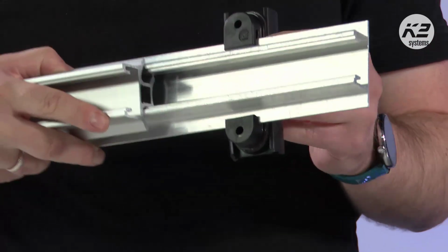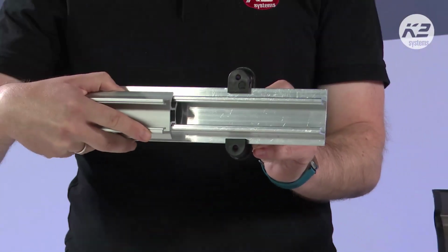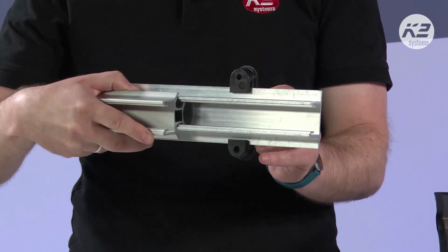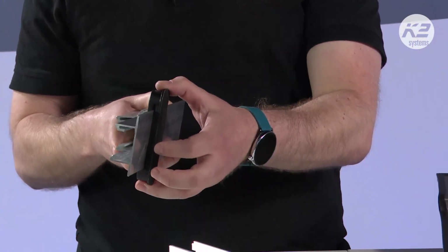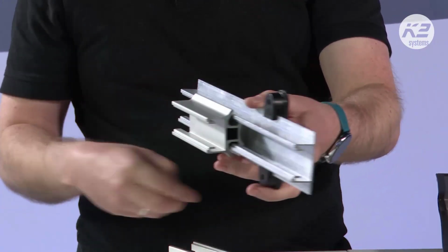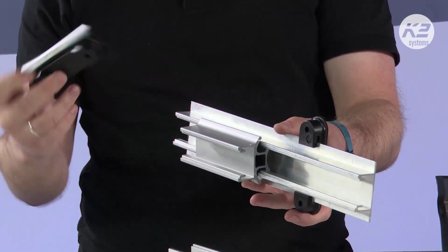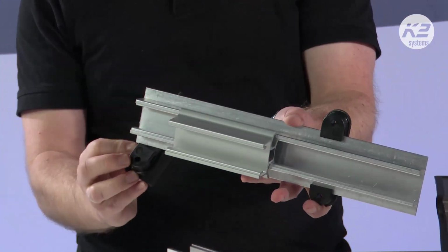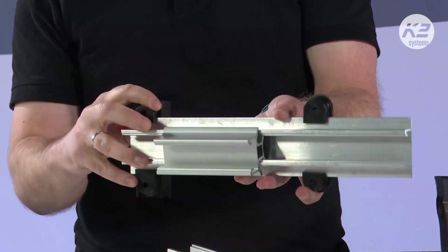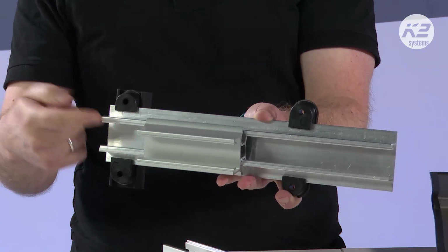You install two basic clips on both sides of your roof. You just bring the BasicRail inside, but now it can go up. And to prevent it, you install every fourth clip turned, so to say. And now this clip is preventing the rail from going up.